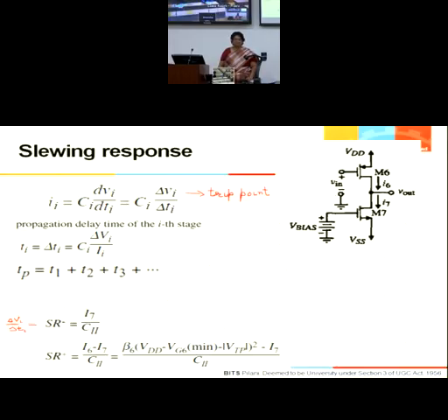We find out the delay for every stage and then add all the delays together. That gives you the total propagation delay, the total comparison time the complete structure will take. In a normal situation, we don't do that. We find out the TP expression in terms of poles P1 and P2 by using the charging and discharging equations of Vout with respect to Vin in the time domain.